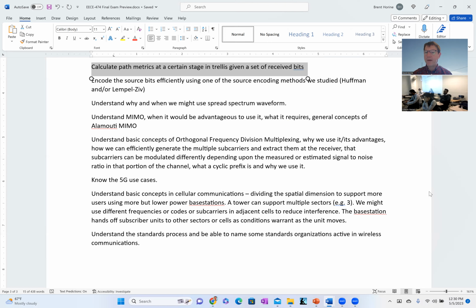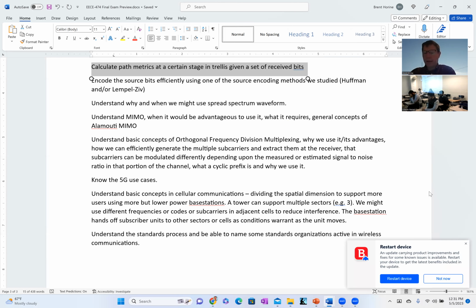Or if we're using fast hopping, now we're hopping to more than one channel for a given symbol, right? So we're trying to send a symbol, but we're hopping really fast. And now if we have a narrowband jammer, then we just lose a little bit of that signal energy, or it messes with our estimated signal energy a little bit, but only when the frequency hop and that jammer are at the same time.